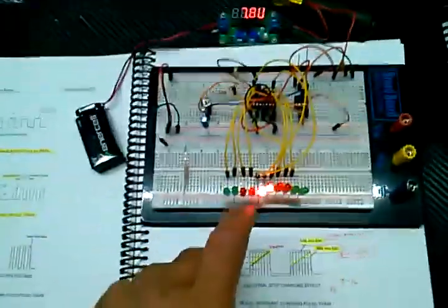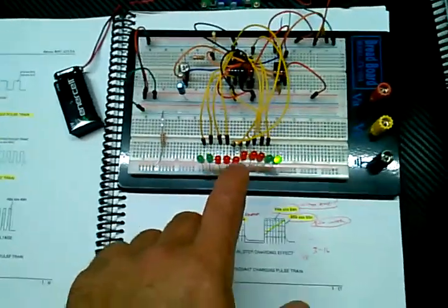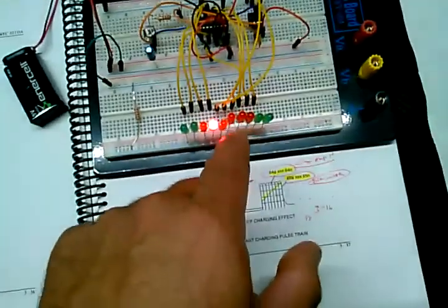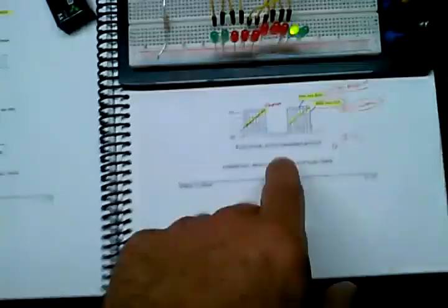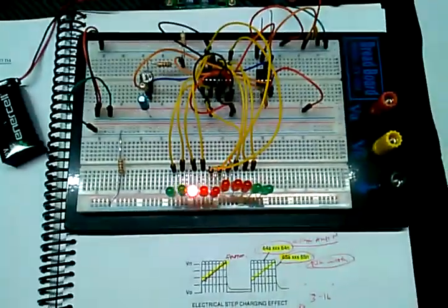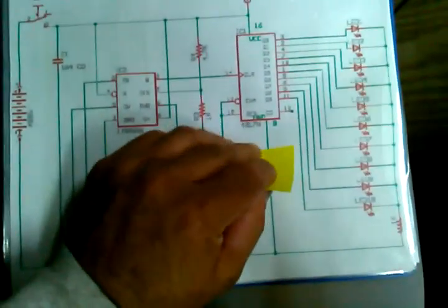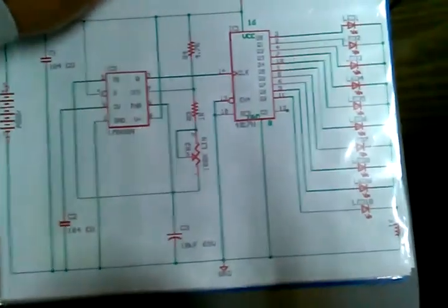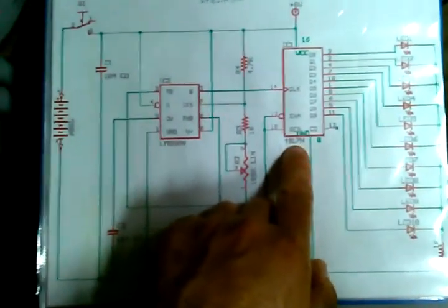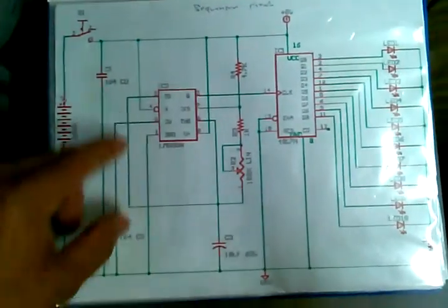Now imagine that each one of these is a silicon controlled rectifier hooked up in a network like that. Now we can phase this correctly with a pulse train, and that would be a very interesting experiment. So let me show you how to connect that if you'd like to mimic it. Here's a sequential circuit. I found this online. There are multiple versions of this. There's a 4017. These are the outputs connected to the LEDs, and there's a 555 here, and then this is the control variable